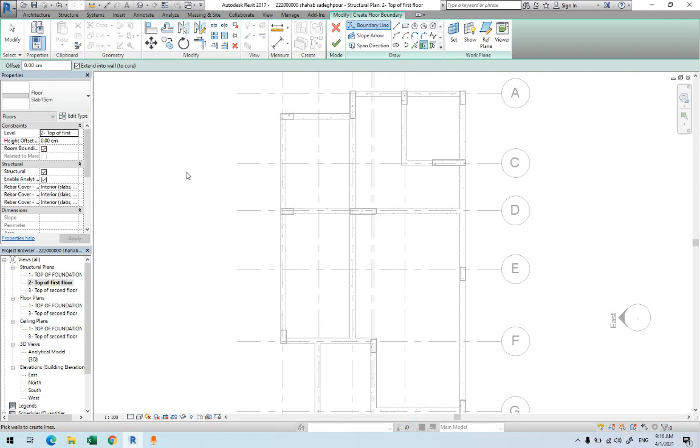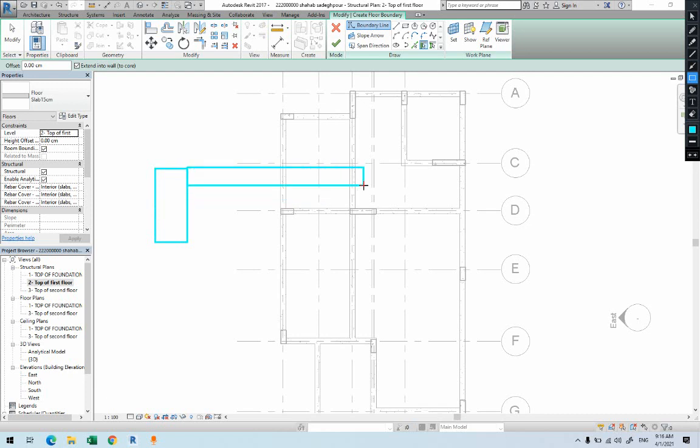The one that we have here is beam slab. So we already did the beams. We're going to place a slab. Since we place the beam, when we place them in a manner like this, the slab will come in this way. This will be the slab. So we already did the beams. We have to place the slab between the beams. So we'll fill the gaps between them, and Revit will join them together.